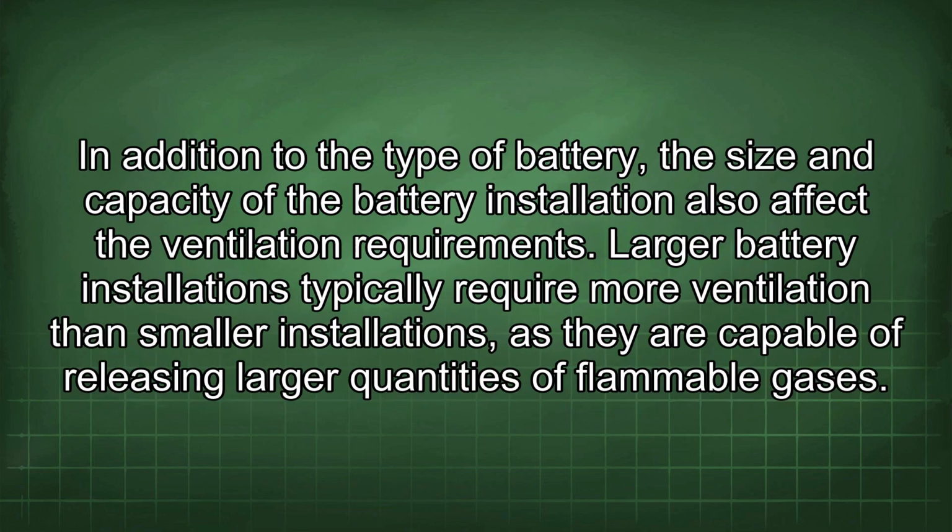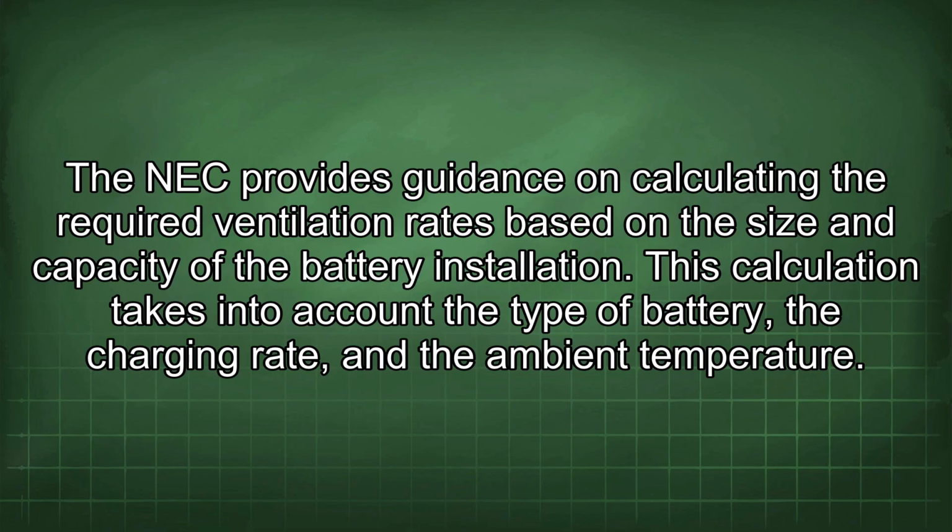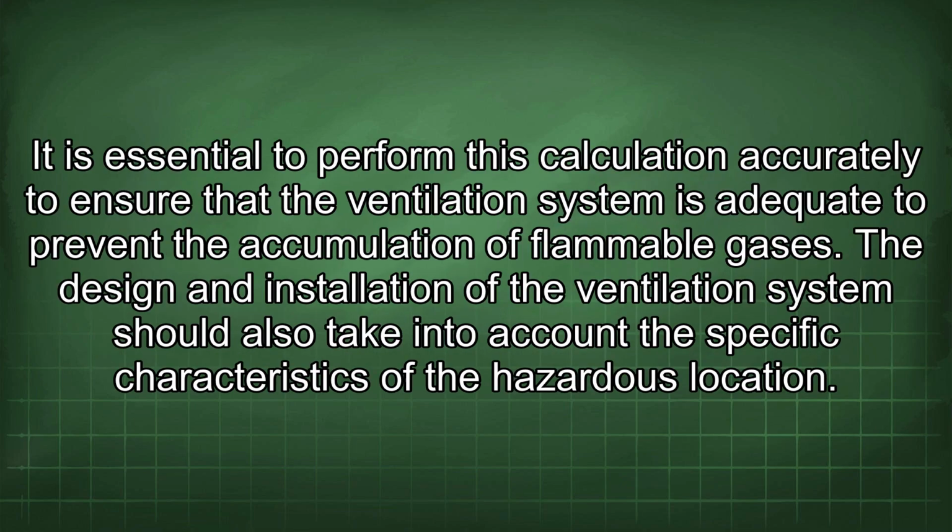In addition to the type of battery, the size and capacity of the battery installation also affect the ventilation requirements. Larger battery installations typically require more ventilation than smaller installations, as they are capable of releasing larger quantities of flammable gases. The NEC provides guidance on calculating the required ventilation rates based on the size and capacity of the battery installation. This calculation takes into account the type of battery, the charging rate, and the ambient temperature. It is essential to perform this calculation accurately to ensure that the ventilation system is adequate to prevent the accumulation